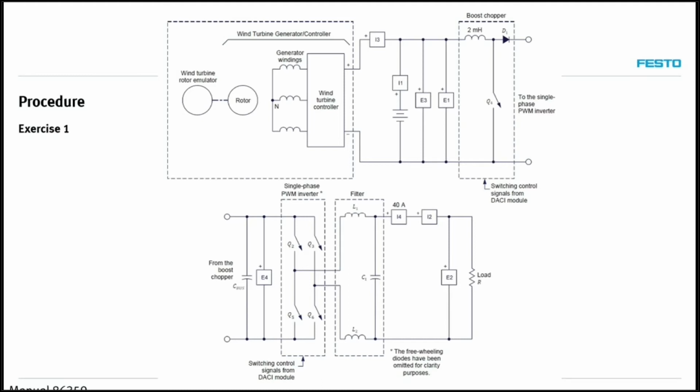So I will leave it there and present you the connections, but first quickly go through it. So here we have the wind turbine emulator connected to our generator with a mechanical link. The three-phase output here going to the charge controller that is connected to the battery to charge the battery. So as you can see, we monitor the current coming out of the battery to see how much power it provides, also the voltage at the battery. Then this is sent to our chopper, which will boost, as I was telling you, the voltage from 48 volts to the 200, so about 200 volt that is required.